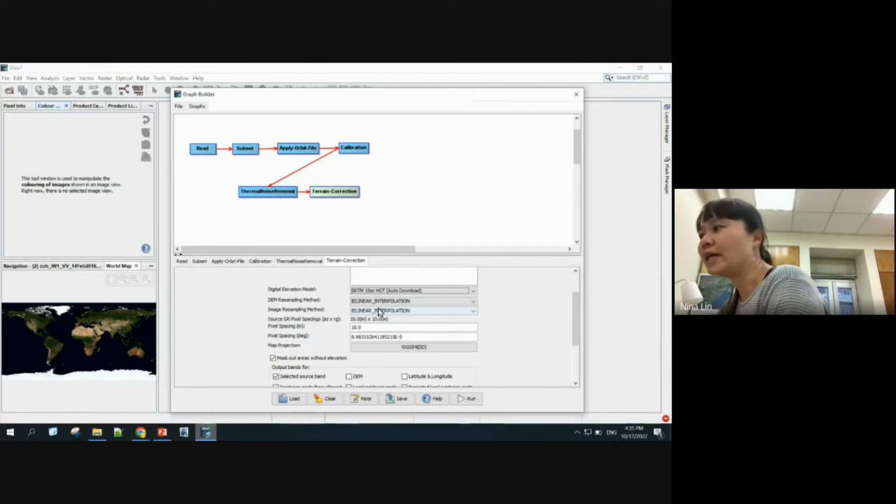The reason is because here we're talking about pixel spacing. And in some cases, people use another term called the posting, like the post on the ground. So pixel spacing or pixel posting is more like how we like to present the data at the ground. We choose to present every 10 meters. But it is not the same as saying the original data contains 10-meter resolution information.